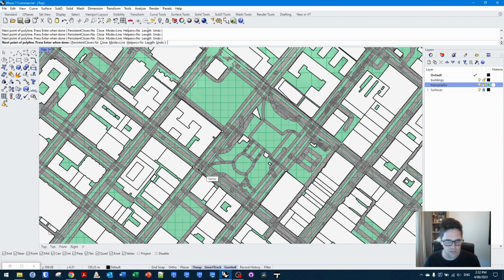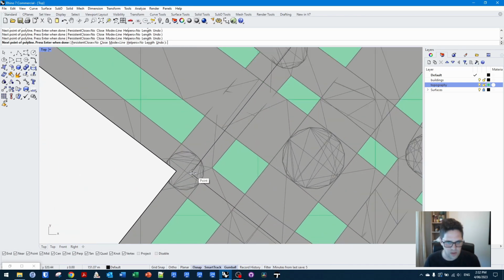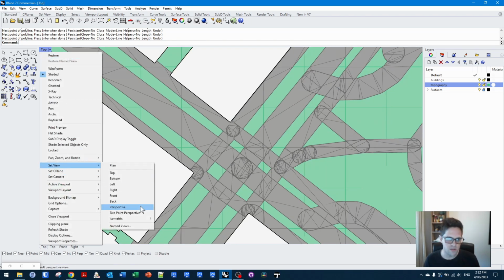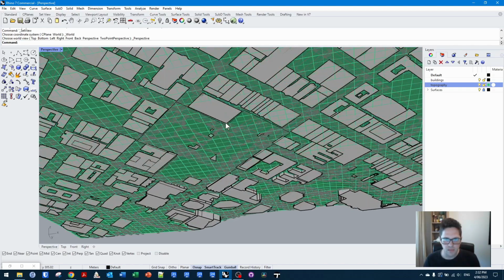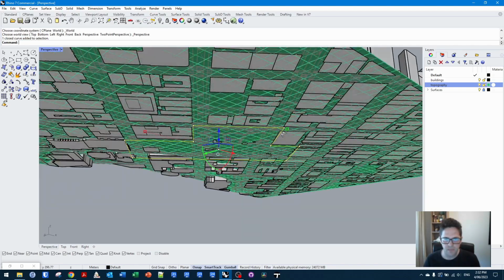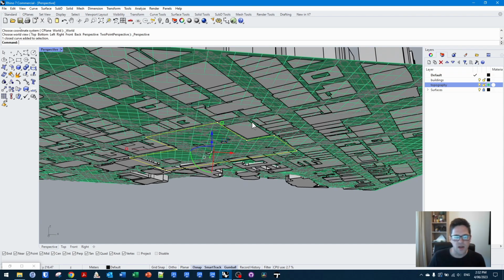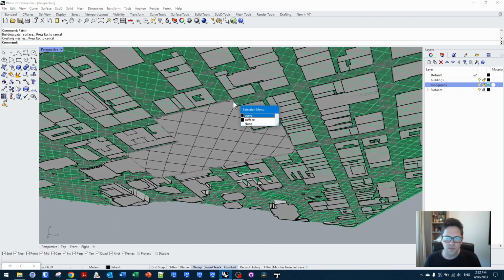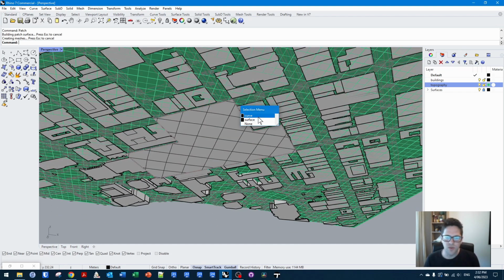And I'll just turn them back on so I can finish off with my snap. So what we've just drawn is probably down underneath the site at the moment. There it is. It should be flat because we drew without snaps. So in this case, I believe we might just be able to patch this space into a surface. There we go. It's up to you whether you want to keep your outline curve or just keep your base surface.